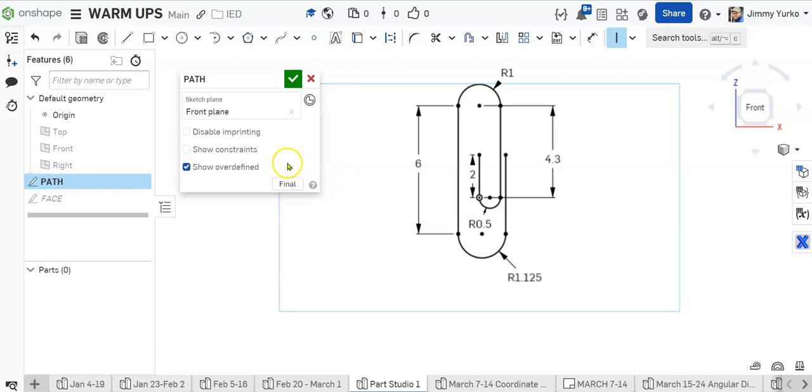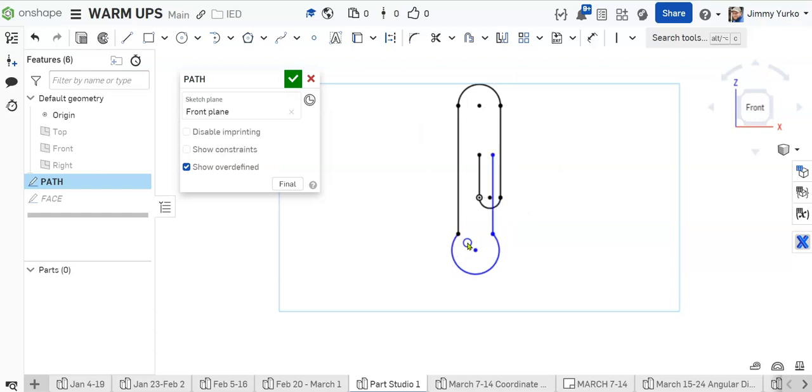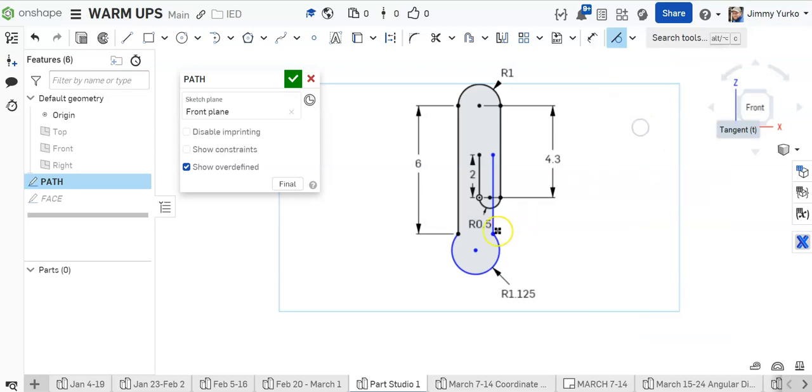You might be missing another constraint, like, for example, this tangent constraint might be missing here, or this tangent constraint missing. So that tangent constraint didn't show up whenever you created this. You'll find that parts will move in ways that you don't want them to. You know, oh, that's not what I want. So that's not tangent. So just tap the tangent constraint and apply that to either of those. You'll see it fully constrains.